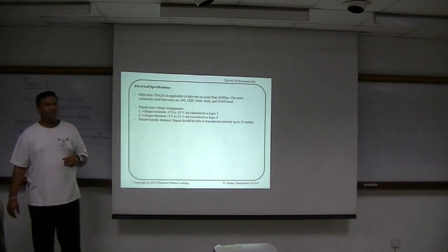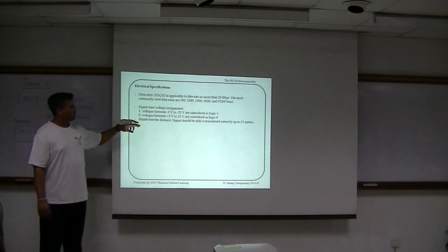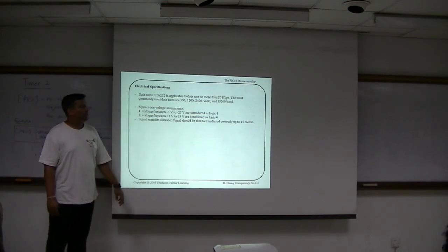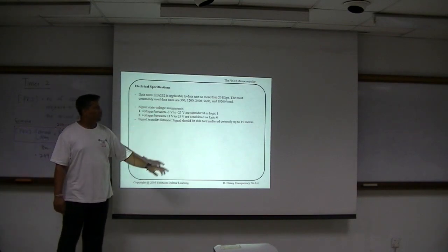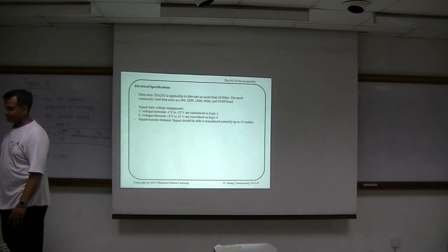Take note that the voltage assignments are actually different. The voltage between -3 to -25 volts is considered as logic 1. Voltage between 3 volts to 25 volts is considered logic 0.